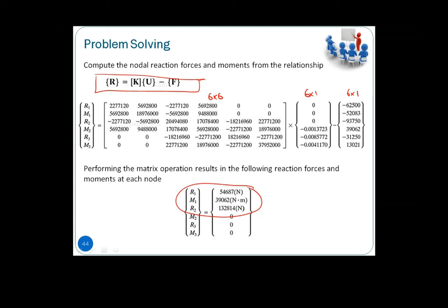From there, one element has 2 nodes, 4 degrees of freedom. Then we have built the elemental stiffness matrix of 4 times 4, and the load matrix is 4 times 1. Then from there we can solve to find our displacement, or what we call the deflections due to transverse loading in this case. All right.